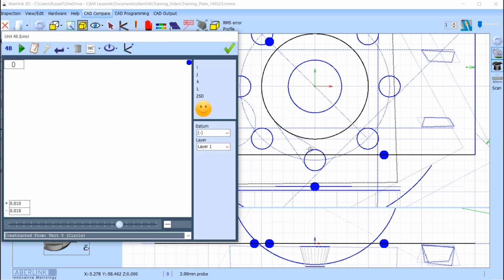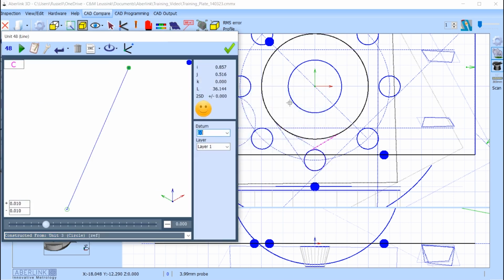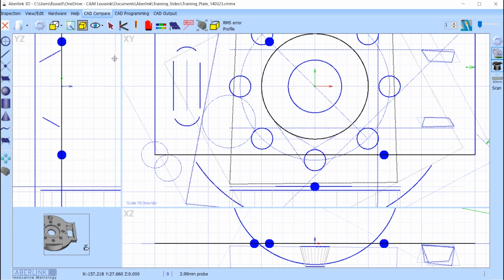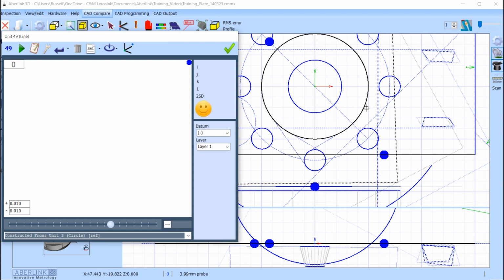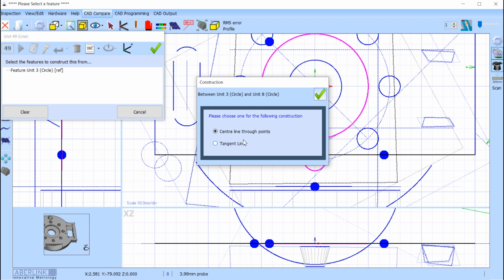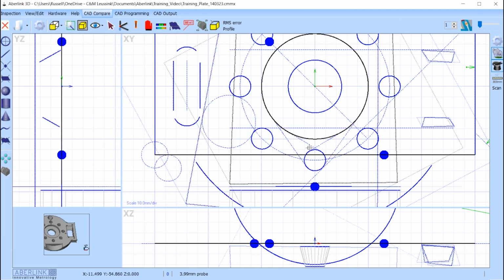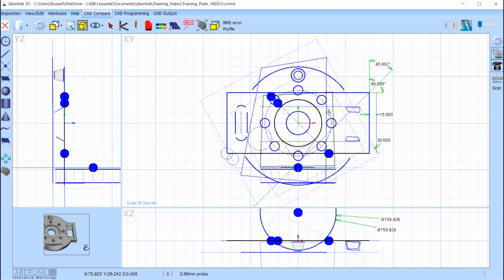We can now do this circle here and here. Tangent line. The opposite way. You want to put a line on the outside tangent. Select the line, the circle. Select the circle. Tangent. There it is there. There are 4 different options you can achieve just by selecting the circle where you indicate needs to be tangent to. We can also do point offsets.